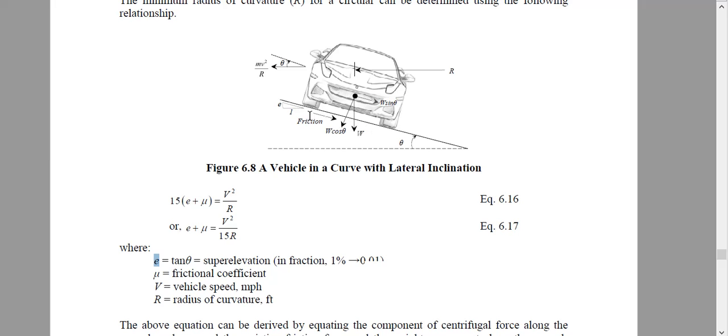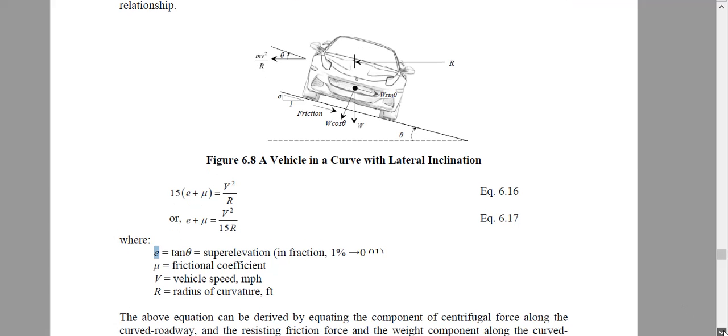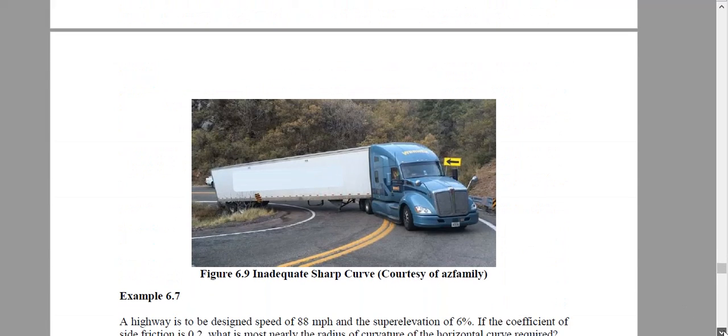How do we calculate that friction? There is a frictional coefficient for this road, and we can calculate it, but we use this equation to balance my velocity. Something else, this is the radius. Another photo will show this clearly. If the radius of this road is not sufficient, it will be very difficult to turn. If I have more radius, I can maintain a higher speed.